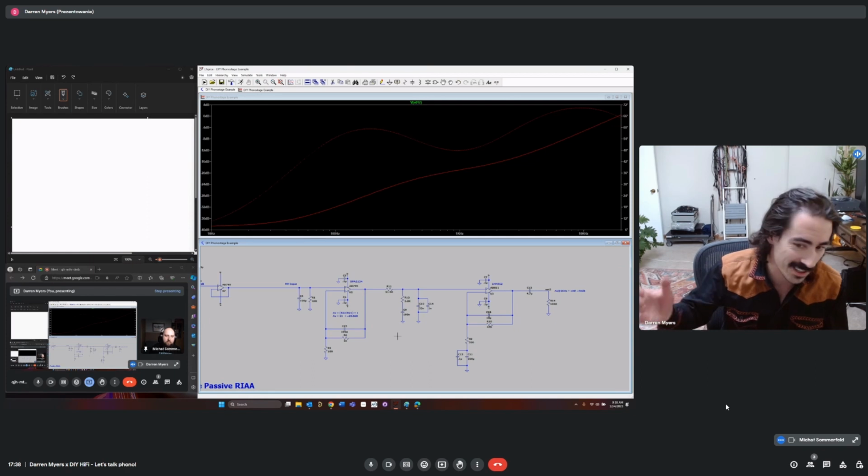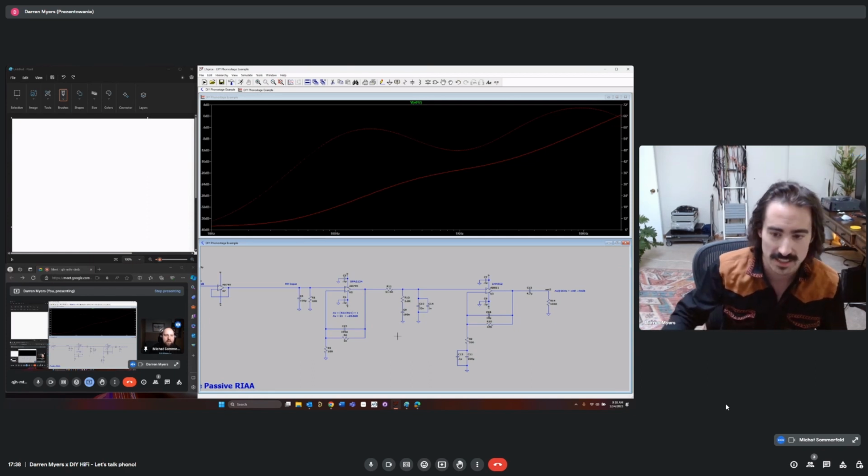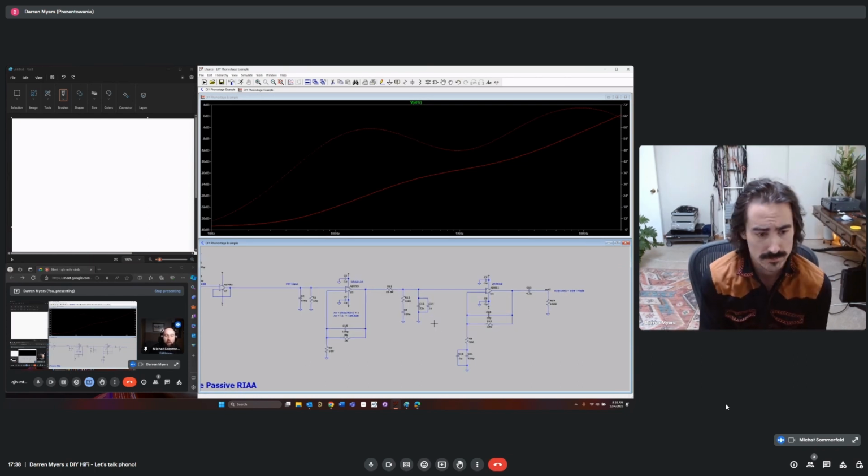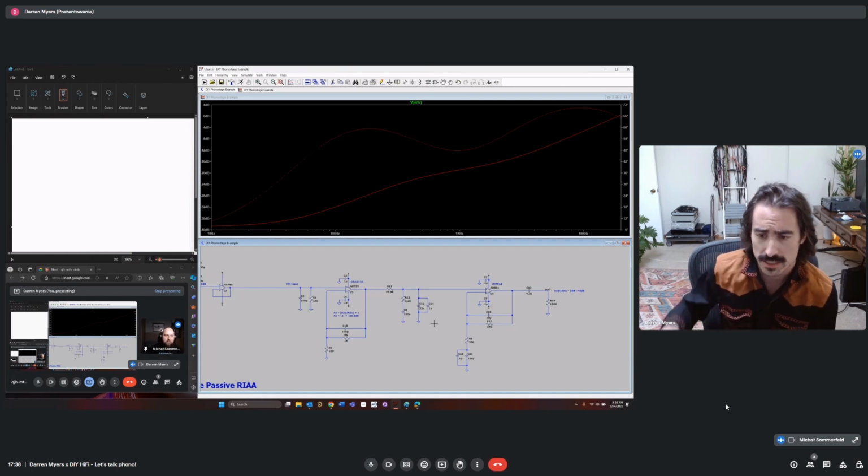And then the resistor values, you can always use series resistors. You can make whatever you need by splitting the resistance up and putting resistors in parallel or series or a combination of parallel and series to get these odd values. You're better off doing that than finding high tolerance odd capacitor values. I don't recommend it. I recommend sticking to these big standardized values. Yeah, and if you can't find high tolerance capacitors, just use smaller values in parallel, because their error will cancel out. Right. Yep. Exactly.